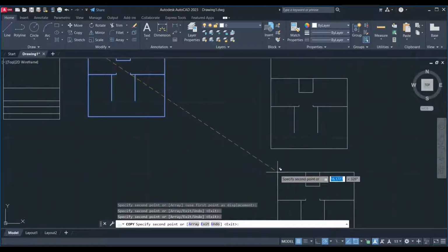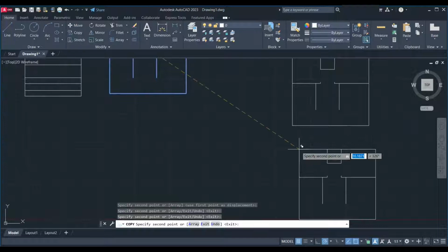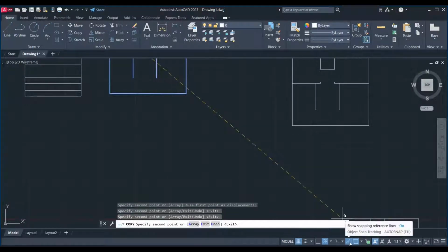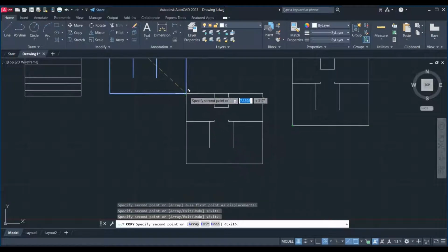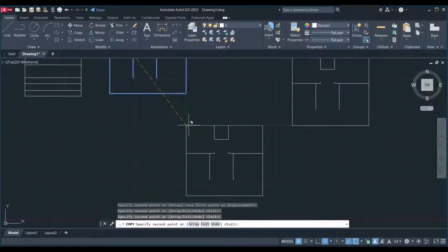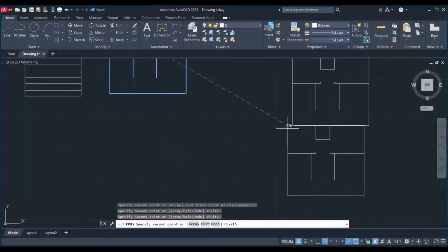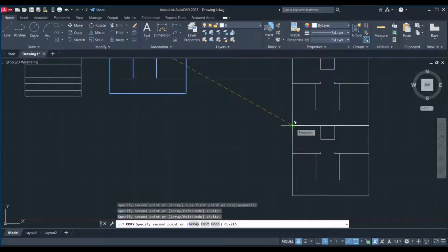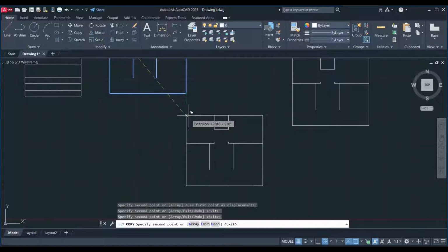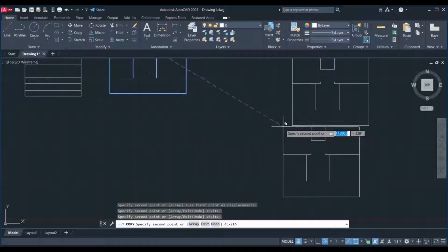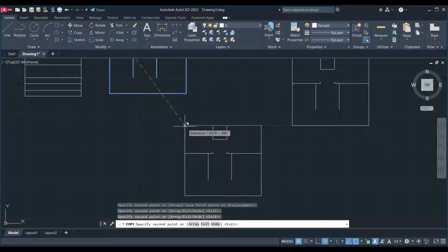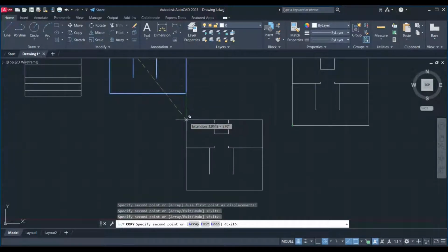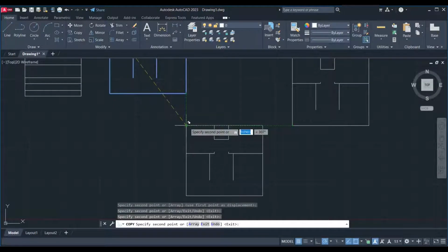Even you can use another drawing aid, that is Auto Snap, the same auto drag. I wanna click on the intersection between these two green guidelines. Do you see? So I move the cursor to this point and move straight to the left and move up to this point and come back. Do you see? It gives me the intersection I want. So simple. Click on the intersection. Finished.